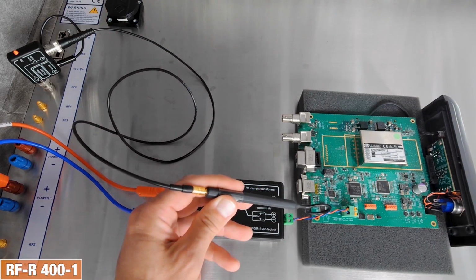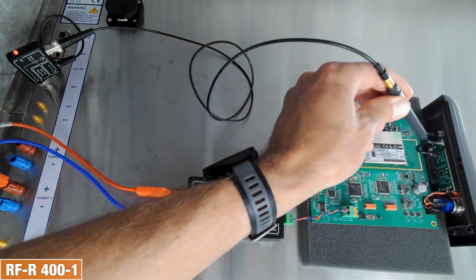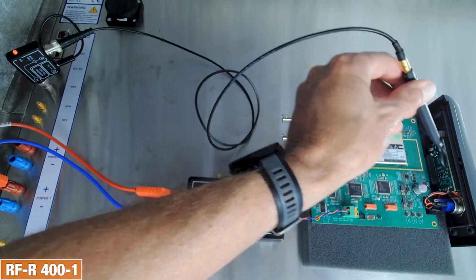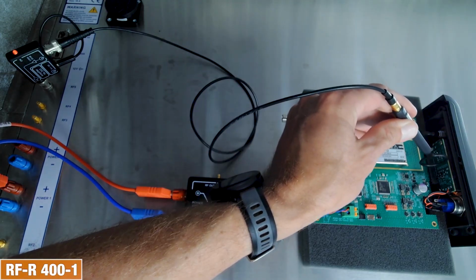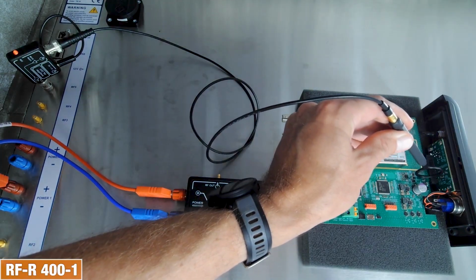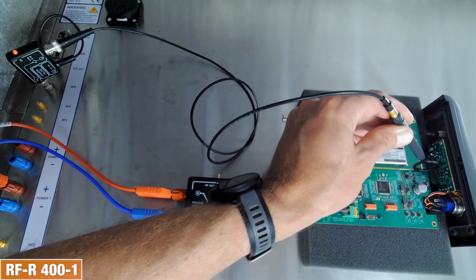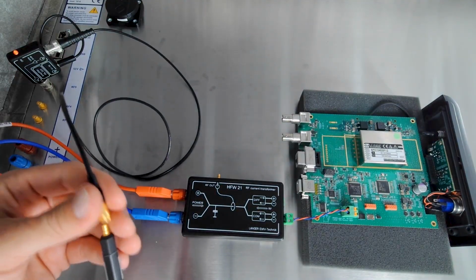You can measure on cables here. Or also when you have a connector, a board-to-board connector between this PCB and this PCB, there you can measure the RF currents which are coupling over this connector here. And if you see that there is a problem, then you use some smaller probes.